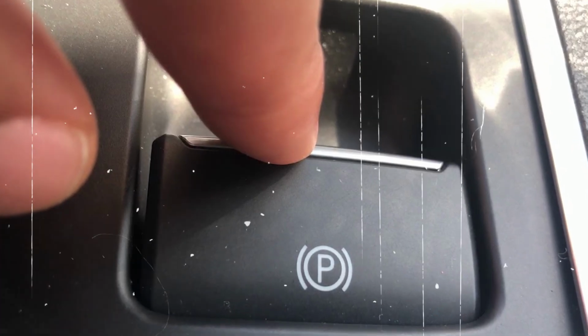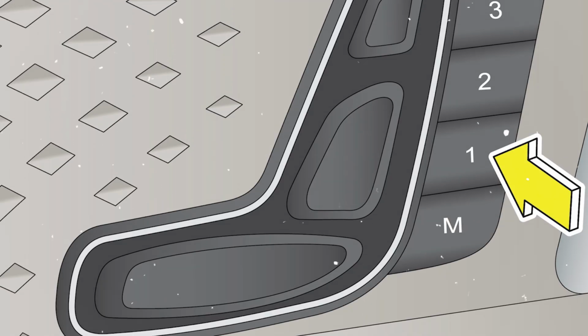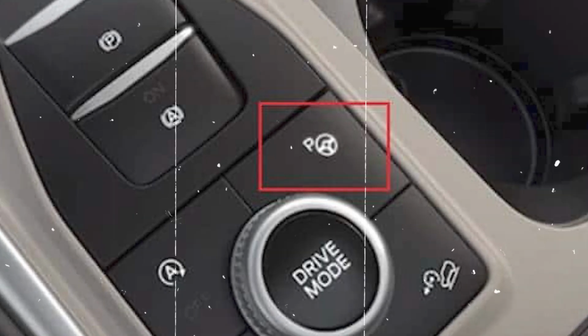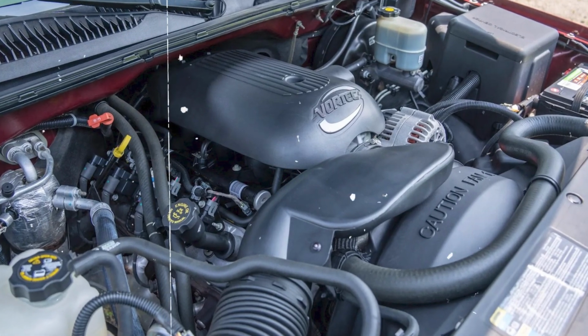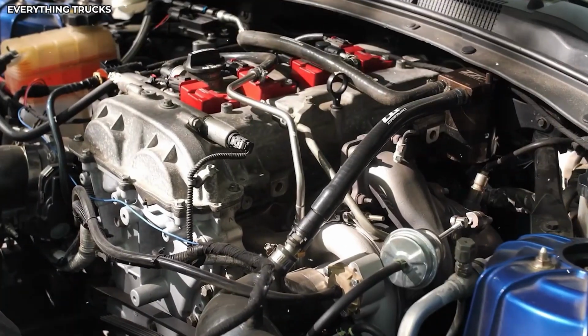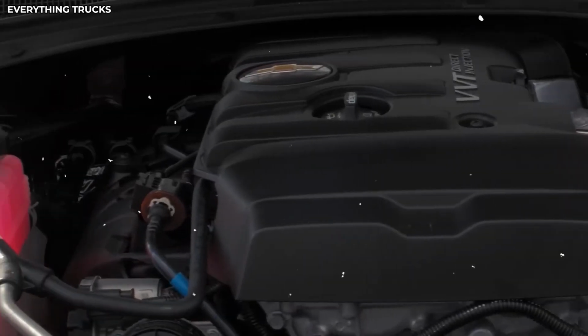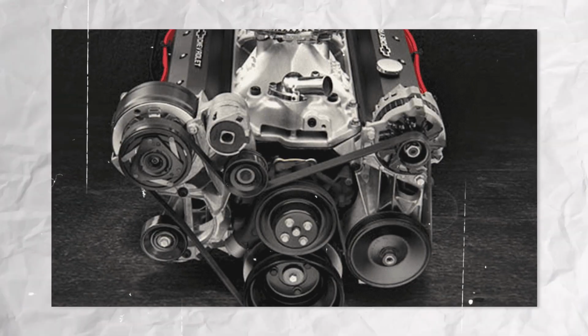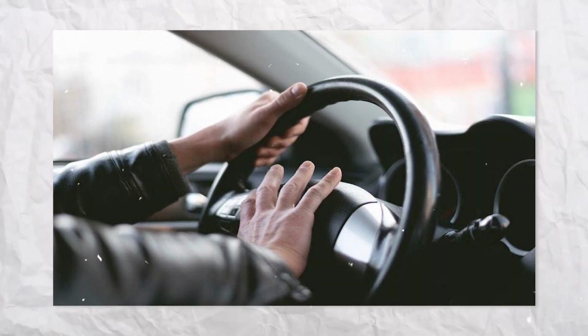I recommend performing the simple 30-second reset procedure every oil change, approximately every 5,000 miles. This prevents conservative adaptive learning from building up over time and keeps your Ford driving with the aggressive throttle response it had when new. The complete battery disconnect method is worth doing annually or whenever you notice significant throttle response degradation that the simple reset doesn't fully address.